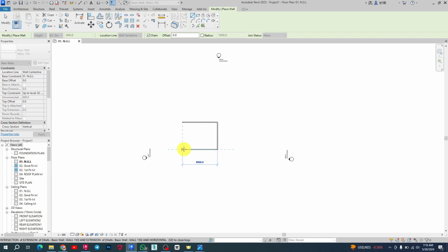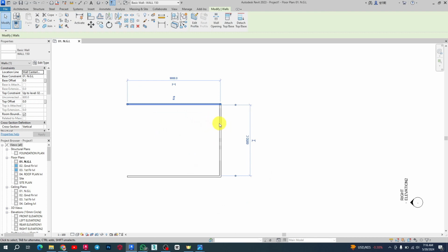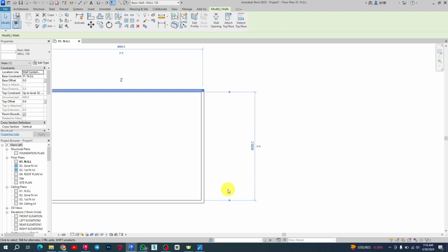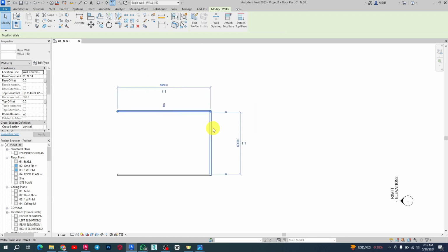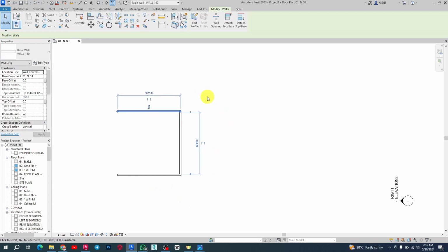So it's actually easy for you to do so many things in Revit. Let's say I just sketch like this. You want to revise this drawing. I want the internal aspects of this, from here to here, to be 6 meters. So I'm using millimeters to put 6,000. You see the line that you selected is going to be the one to move. So I want this one to move again. I want it to be 6,000 again. So I'll not have to be typing the dimension or stretching, right? Remember, they say Revit is revise and edit.